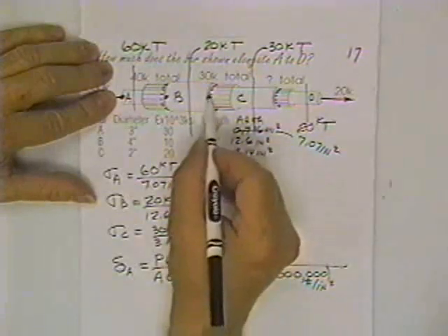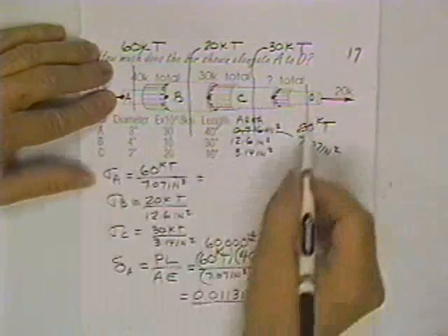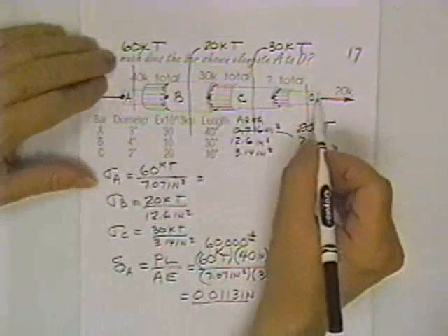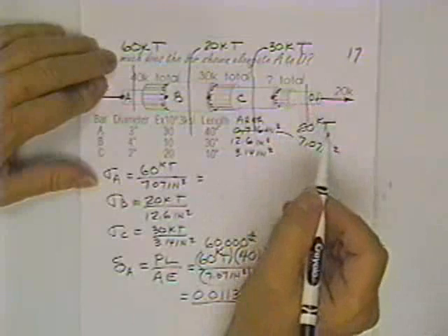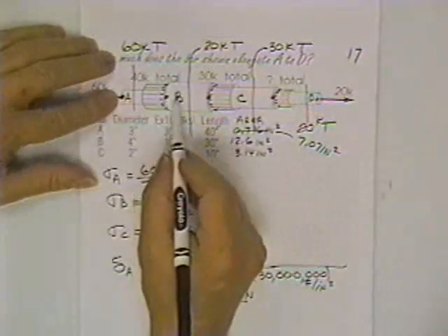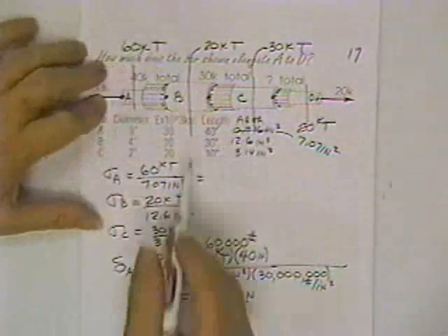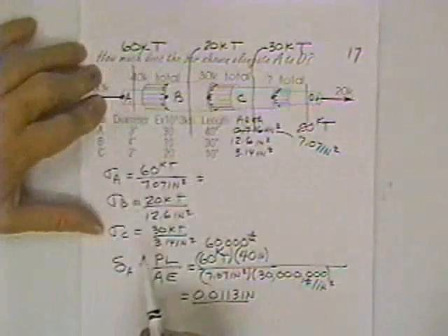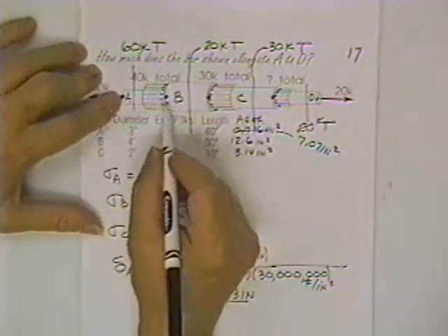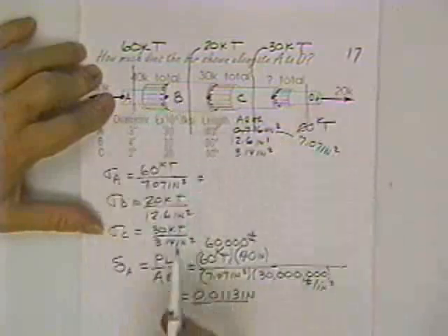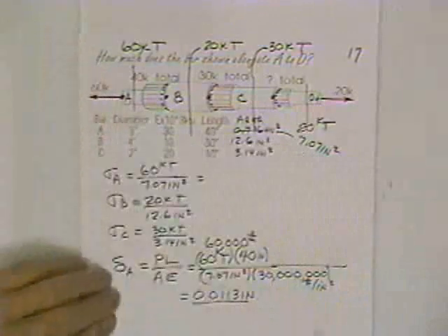Now then, we can do the same thing for the next section and the same thing for the next section, and if you'll give us information on bar D, I don't see it anywhere, then we'll get the same information for this section and we'll be able to tell. Some of these little pieces may get longer, some may get closer together, not in our case because we have tension everywhere. But if they get closer together, we'll just subtract that. We'll add how far they get apart, add up all the numbers all the way down, and know where did point D go with respect to point A?